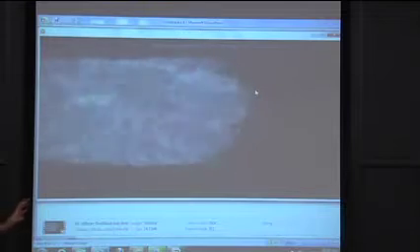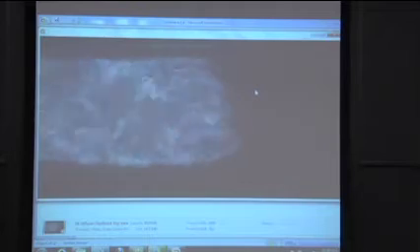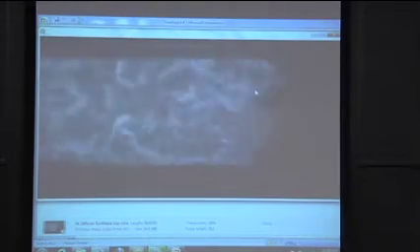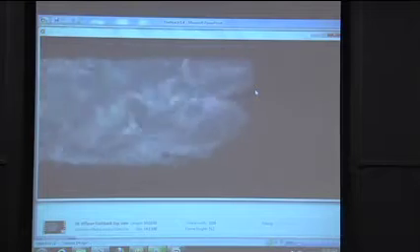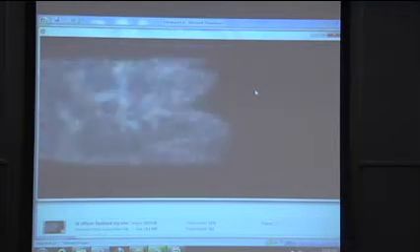Very, very likely what's happening here, and by the way, this is a really interesting subject for future research, is the flame is interacting with the hydrodynamic stability of the turbulent boundary layer. You know, the turbulent boundary layer is itself unstable. It has these Tollmien-Schlichting waves, which you might have heard of, and these lambda waves. And the flame is interacting with those, and it's changing their character in a really interesting, unsteady manner.